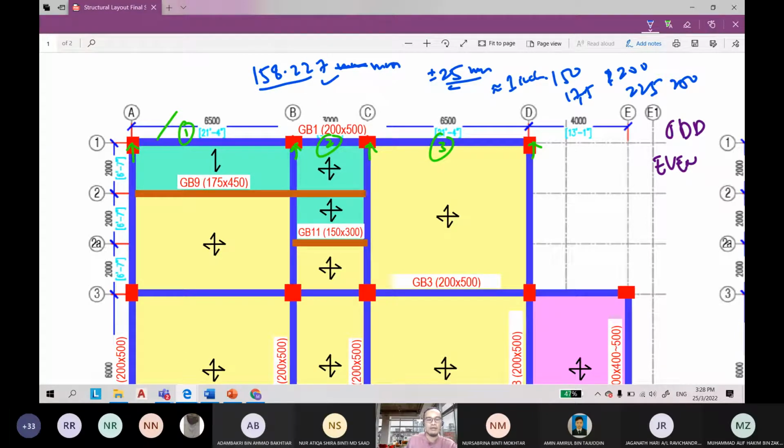But how can you imagine the laborers or the construction workers on site setting up this width? They ask, what's the width? The width is 158.227. How will the contractor set up for this? Maybe if you use steel fabricated inside the factory, we can set up, but the factory also uses this practice, which is the increment of 25 mm.